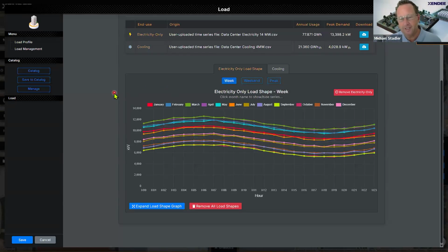If you go with time series data, yes, you get very detailed results, but you're also risking that you're designing the system on something which might be an outlier. This is why maybe a multi-analysis is good, or maybe going with historic data, which is more an average profile, and doing a day type optimization, which takes out the peaks. This really depends on the preference and what you have in mind. When we do these analyses, we typically do both: a day type analysis, and then a time series analysis to see what's going on here.